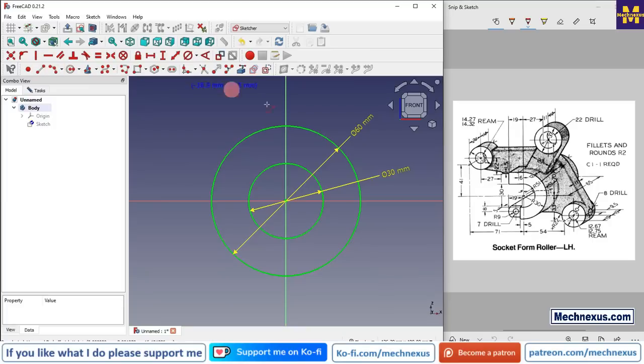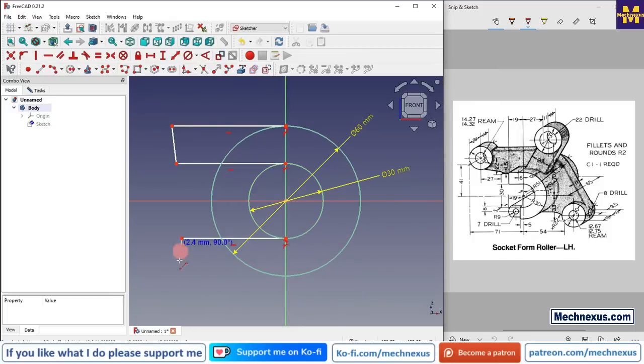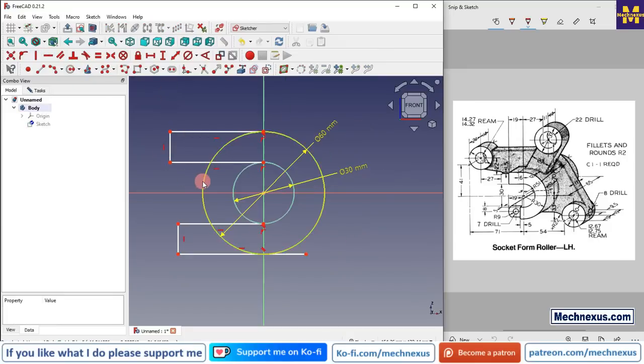So we will select the line tool and create a rough profile. In a similar way we will do the bottom side. Select the line tool, make it tangent, make it horizontal, and this one vertical.